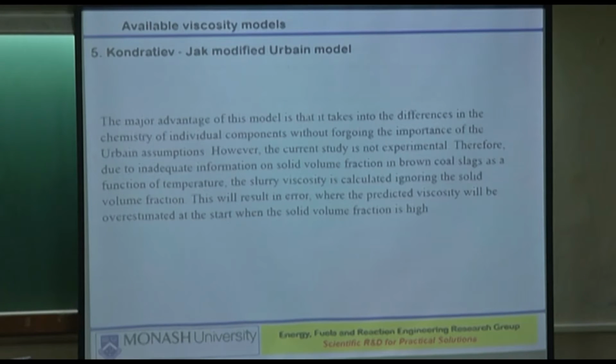Now, whether that amount of time is available inside or not, that's the question. Ideally, you won't give it much time to stay inside the gasifier, because you don't know what it will start doing. Ideally, you would like it to become sufficiently molten and then flow, even if that means some amount of solid fraction being present, who cares?